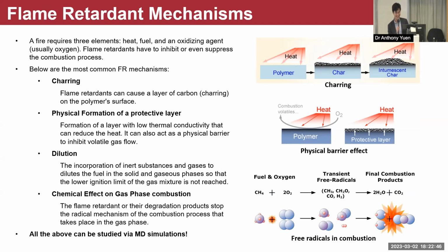But in most cases, the main effect of fireproofing a material is the charring effect. Charring is carbonaceous atoms forming at the surface of a polymer. By itself, it's not very heat penetrative, so it protects the inside material from burning by acting as a protective layer. So the first two work hand in hand with each other.